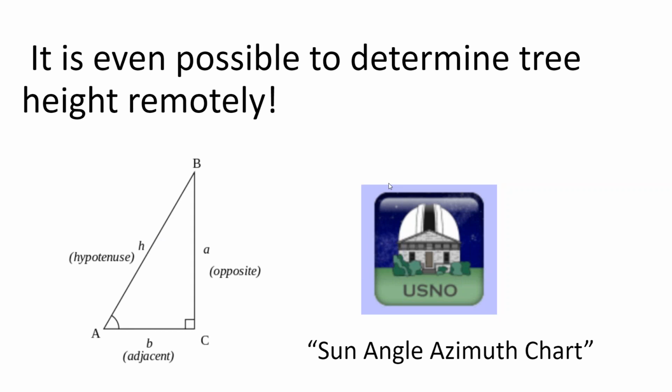When I was just doing residential projects, I thought that commercial site evaluations would be harder than residential, but they're actually easier because there's usually not a shading issue that can't be solved with good old-fashioned trigonometry. On a commercial site, how tall is the air conditioner unit standing off the roof? Oh, you need to be so many feet back. Well, actually, on a commercial roof, if there's any kind of elevated anything like a building wall or a piece of electrical equipment or a vent, you want to be pretty far away from it to begin with. So commercial layouts are actually a little bit easier.